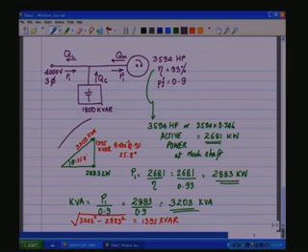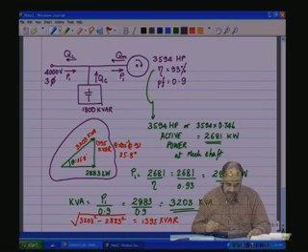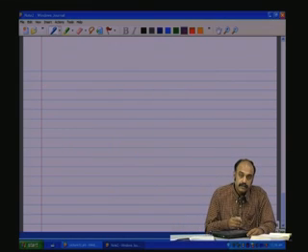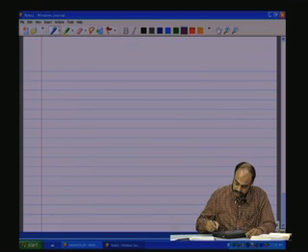So, this would be our power triangle. As far as this portion, that is the load portion, is concerned, without having considered the capacitance reactive circuit that we have put in there. Now, if the capacitance circuit is put, which is 1800 kVAR rated, that capacitance is going to generate QC.